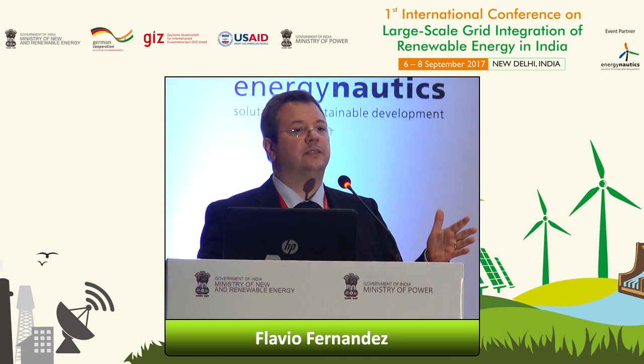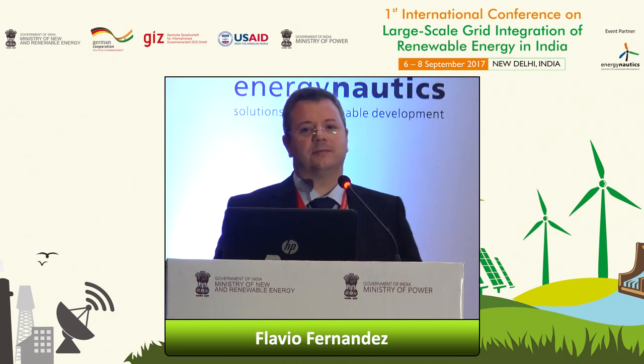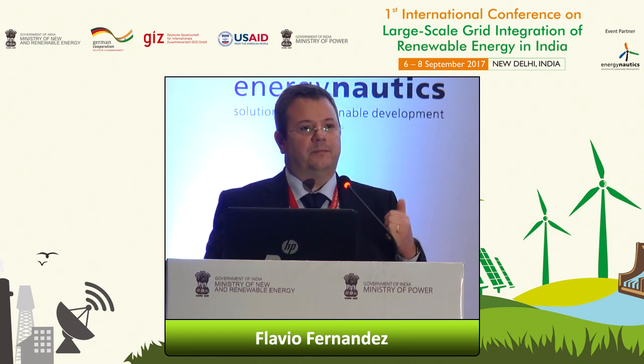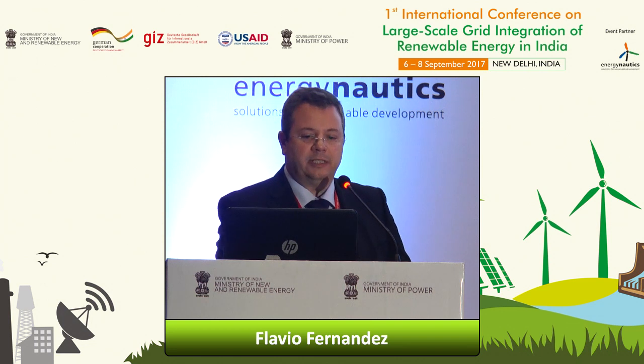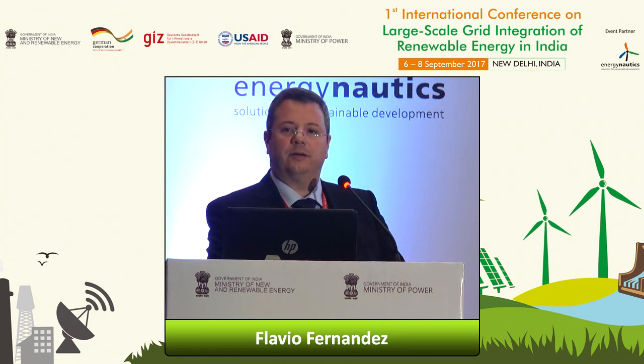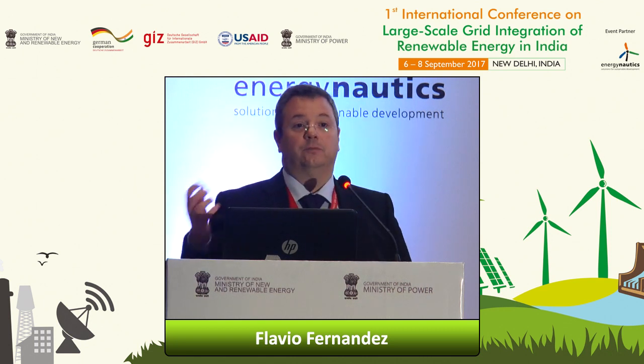Finally, model validation is also a good point. When we present the models, sometimes people ask, well, have you validated them or not? Maybe a good experience here has been made in Germany. In Germany, normally if you want to connect a power plant to the grid, you need to undergo a certification process, and to certify the process, you need to have a certified model.